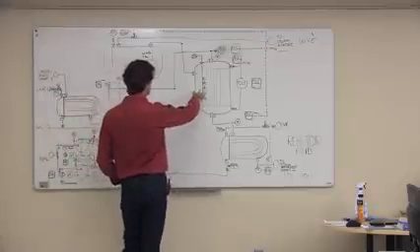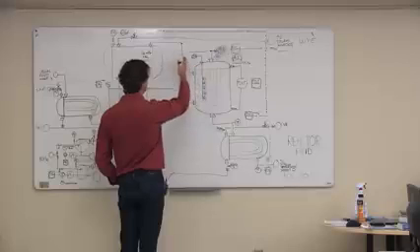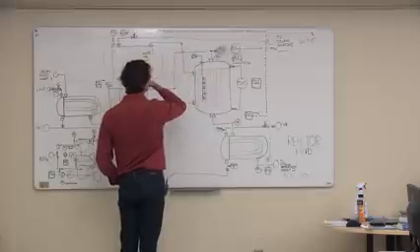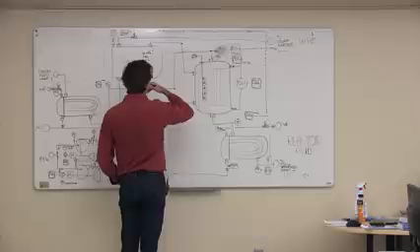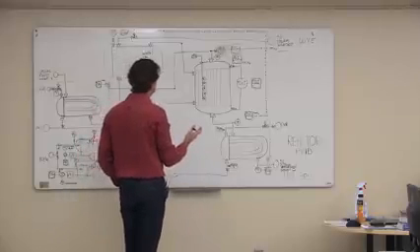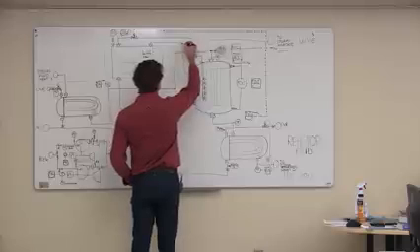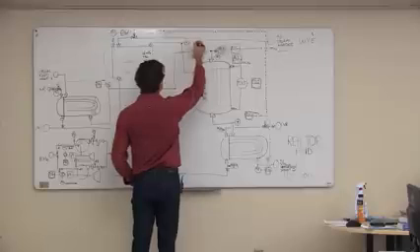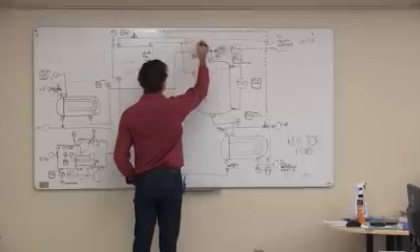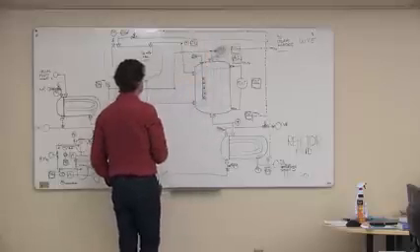It goes through the heat exchanger. Assuming there's not a lot of change in pressure here, it's just changing phase, so it's coming out of here in the changed phase. Measuring the temperature isn't going to be terribly useful. You might want to do it anyway, but it should basically be reading the same temperature. The only difference is that there's going to be a slightly different pressure there. So you can put it in there. If they're different, then you'd start to wonder and maybe troubleshoot the process.